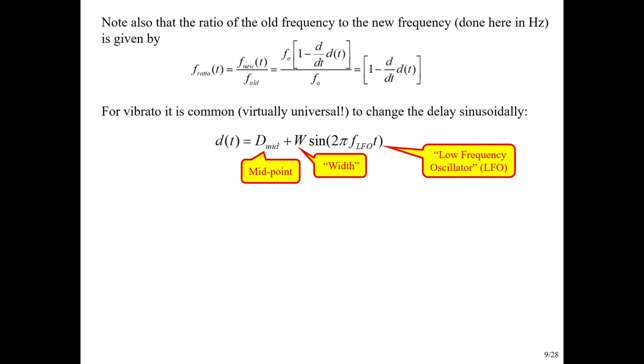And in most musical applications of this, digital audio effect versions, not physically wiggling the string in one way or another, or wiggling your tremolo bar, as Fender calls it, or vibrato bar, as everyone else calls it, we need to have some sort of electronic way of creating that delay. So let's write an equation for the delay. There's going to be some midpoint, right? The source is moving back and forth. So there's going to be some midpoint, and that's the delay corresponding to that.